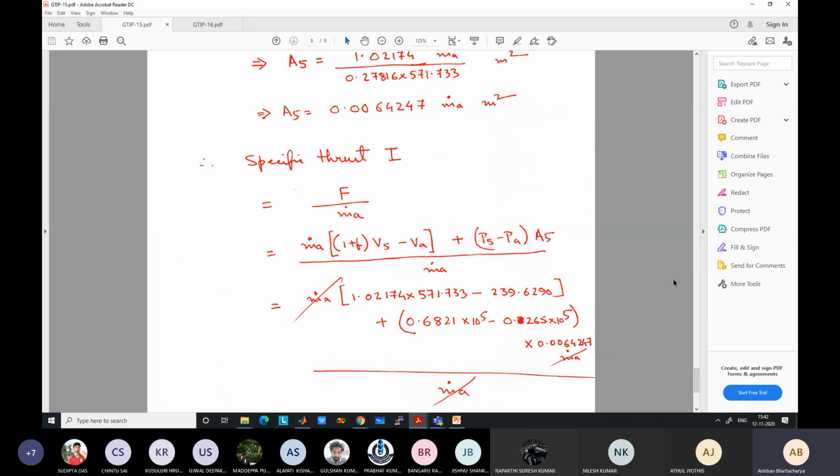Basically altitude and Mach number: at which altitude the flight is, and the Mach number at cruise velocity. We want to see the effect of these two primary parameters, RC, the compressor pressure ratio, and the turbine inlet temperature T03.